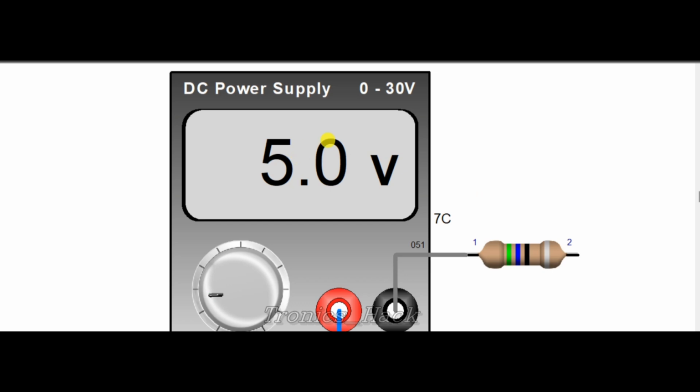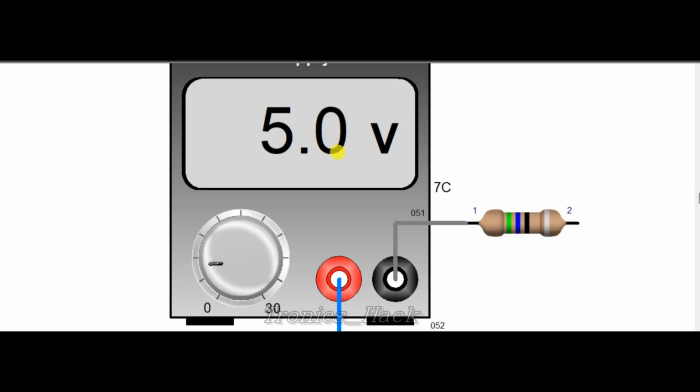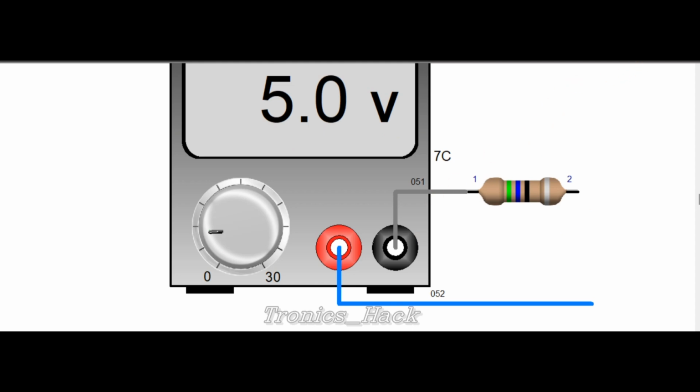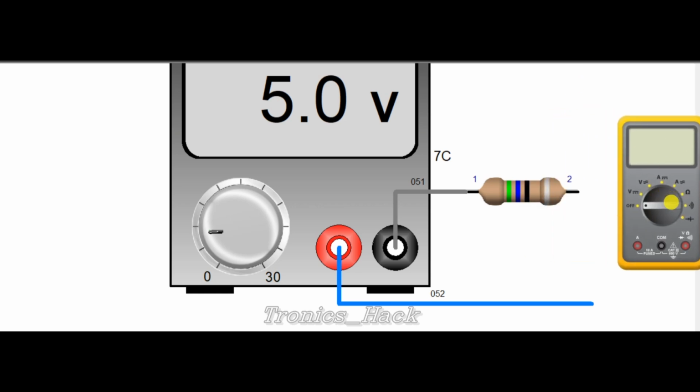To that place, I hook up a DC voltage of 5 volts with a resistor. I want to show you the formula that I just gave you. This is a resistor. Let us measure the current. If we want to measure the current, you have to put your multimeter in series. Let me show you: we have a DC amps setting, so I will use this one, put it in that place, positive, and this one in that place, and I get 90 milliamps.